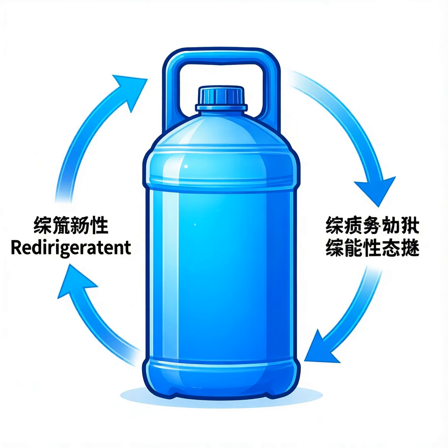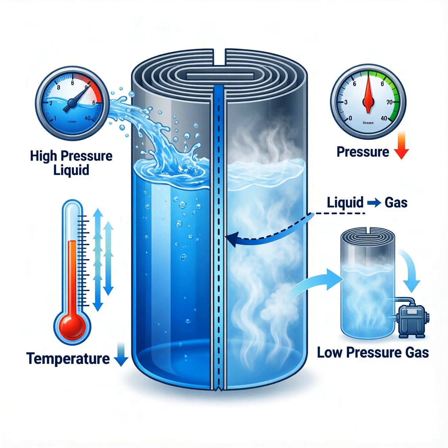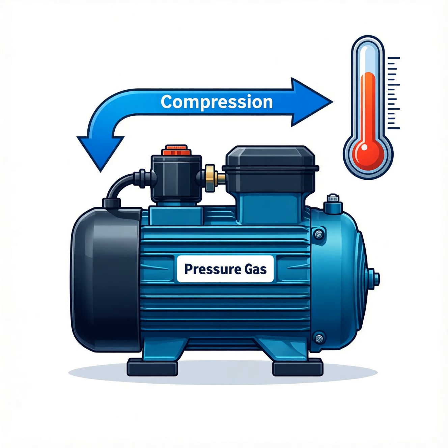In the condenser coil, that hot gas gives its heat to the outside air. As it cools, it condenses back into a liquid. The low-pressure liquid passes through an expansion valve, losing energy. This drop in temperature prepares it for another round of evaporation. The cycle repeats continuously, keeping the indoor air cool. Thus, refrigerant's ability to change states is essential for efficient cooling.